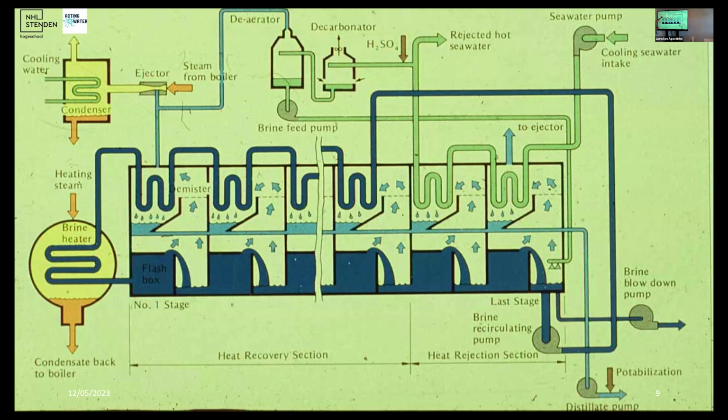Well, in here you also have the steam generator. The steam injector can also be used for the high pressure in the condenser zone. You can see also that the brine recirculation pump can be used to re-inject the liquid in the condenser phase. And sometimes, as you can see here, depending on the number of stages that you have, you have a temperature control, and then at a certain plateau temperature level, you may have to divide your feed a second time.